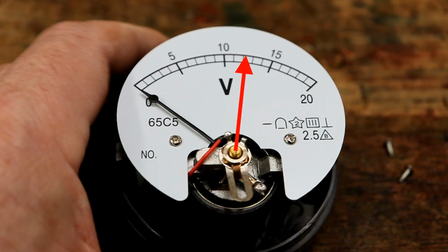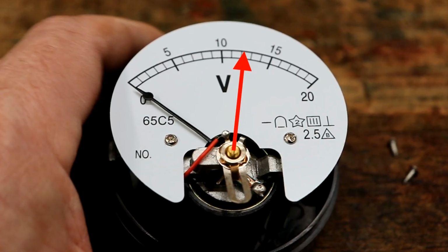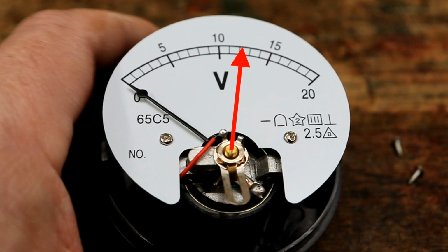Now it's time to start thinking about the graphics that we want to design on the dial. In order to do that, we need to know where the centre of the moving coil movement actually is, i.e. the point about which the pointer moves. We can do that in a couple of ways. One is to use a ruler and actually measure it on the gauge before you take it to pieces. Alternatively, you could scan in the existing dial and put that onto your CAD software and take measurements off that. I'll show you how to do that later in the video towards the end.